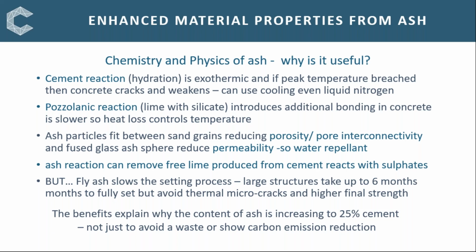The fly ash reaction is slower, and that reduces the peak temperatures. Also, the full strength of the material is achieved and usually exceeded after several months of setting, in the case of large concrete structures. I won't go into the chemistry here, but there are more details in the report for those that are interested.